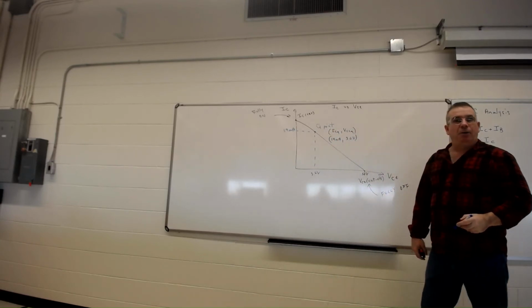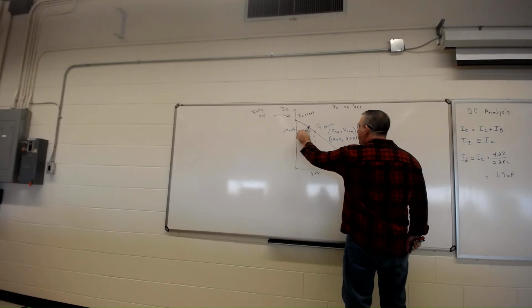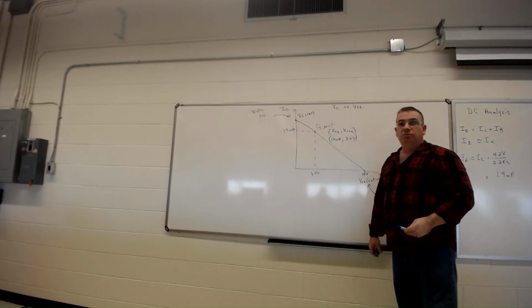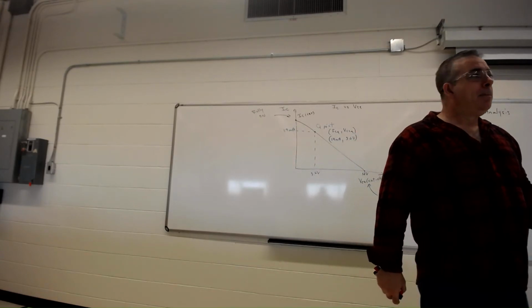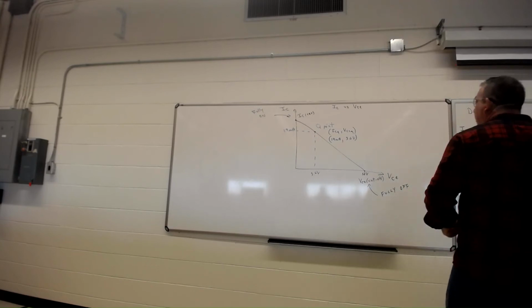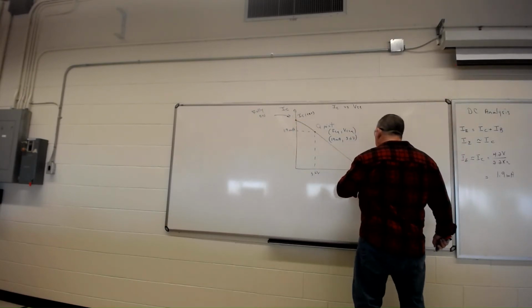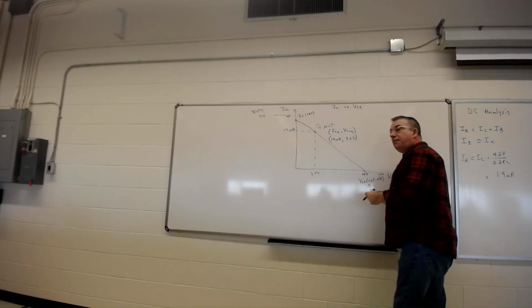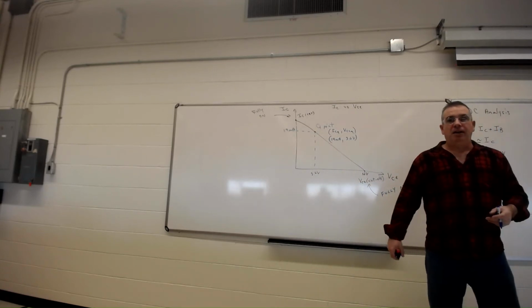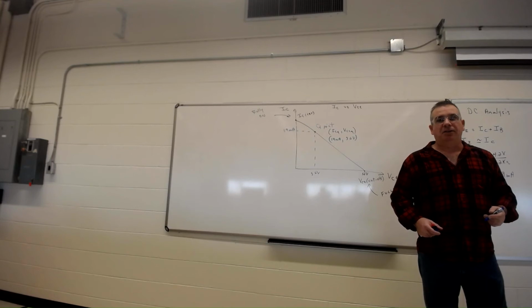And as an amplifier, when we start using it as an amplifier, we're going to make this point go up and down. That's what we're going to do. All right? So we're going to apply a sine wave somewhere, or whatever wave we want. We'll make this point move up and down, but it's going to be between these two points. It won't be fully on or fully off. It's somewhere in the middle, conducting. That's why they call it a semiconductor.